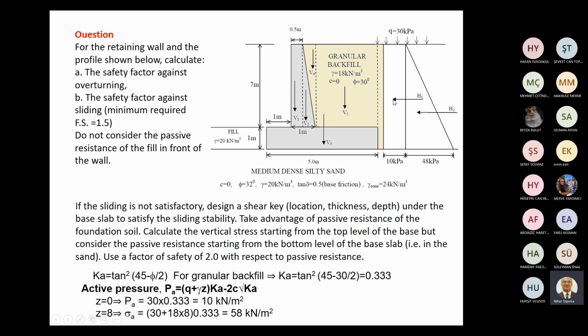Application points are half of the rectangle for the surcharge and 1/3 of the height for the active pressure. We have a granular backfill and concrete wall, and below the wall the soil is dense silty sand.